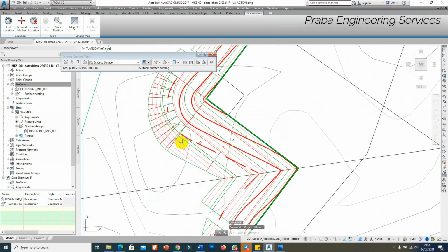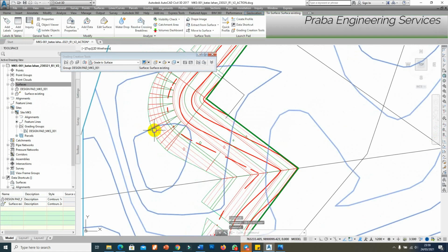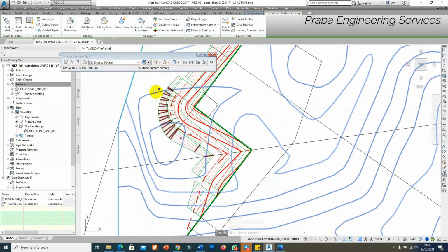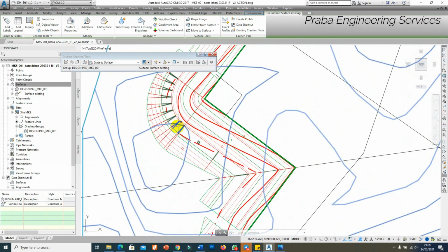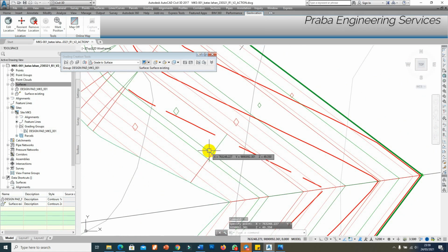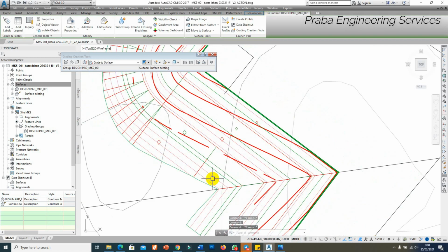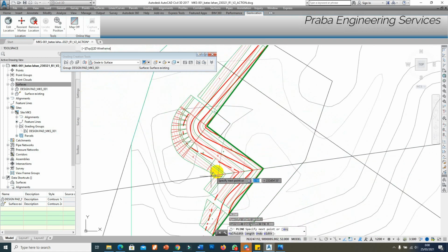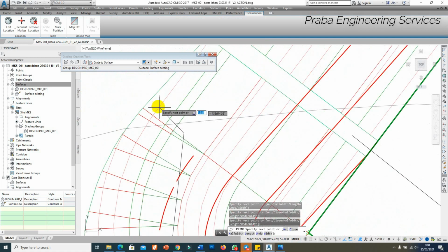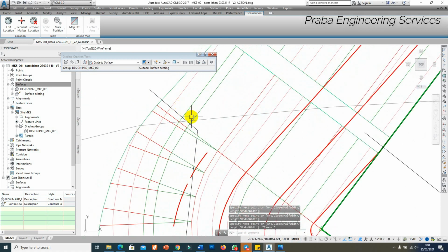So from this one, because the existing location is so high, when I already cut in here, I will add some benches again. I just check the ID. This is 46 and this is 53, which is already 4 meters. This starts from here, so from here in that zone until here, we need to add more benches.